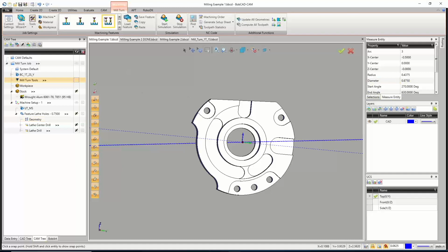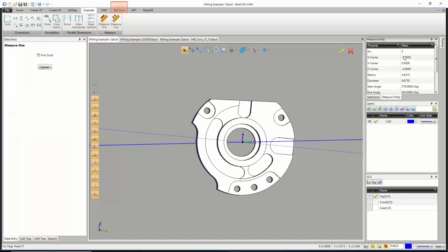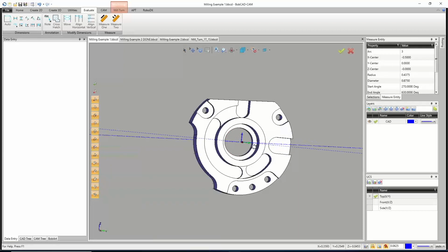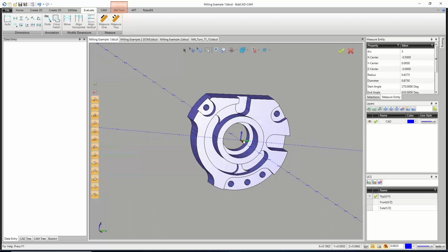I measured that center hole earlier, and it should be that value there, but let's just double check. Yeah, so it's 7/8. I now have a 1/2-inch tool, and I've already cut away 3/4 of an inch. I have about 1/8 of an inch left, so that puts 1/16 of an inch on either side. I'm cool taking a 1/16 out in one pass, but I have to be cool taking a 1/16 out at that full depth. So it's 3/4 of an inch deep, and it's a 1/16.